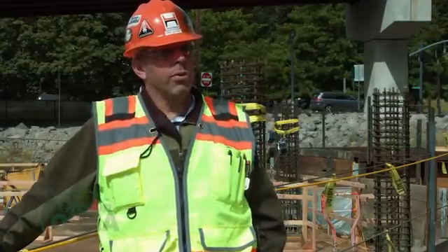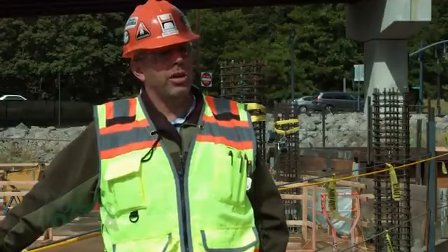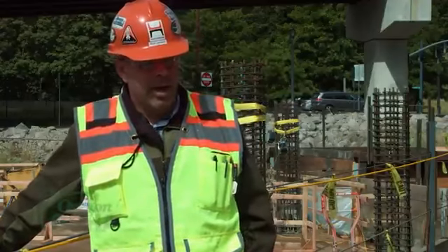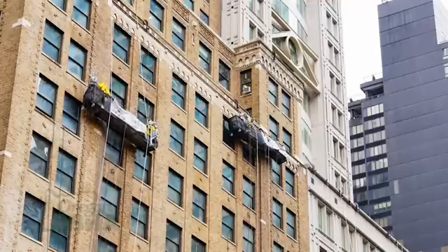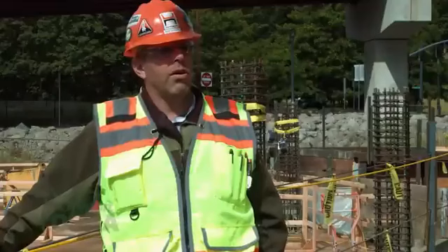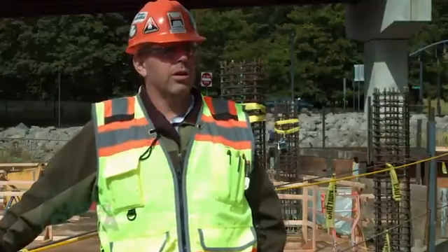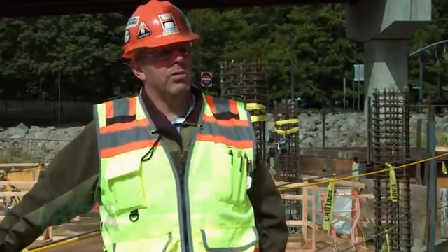that if you exceed the 4-to-1 scaffold height, your scaffolding is tied back into whatever structure you're working off of. On swing stages, there's a whole different set of rules that go with them. I would say on swing stages, you want to make sure that you have primary and secondary fall arrest, and that your fall arrest system for your workers on your swing stage is completely independent of the swing stage itself.